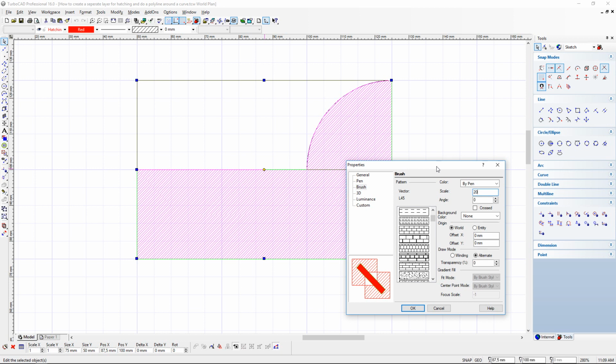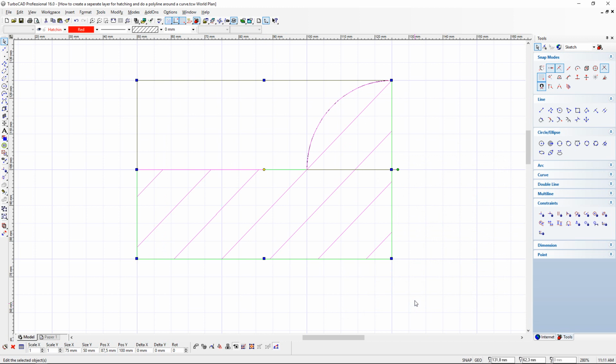But now in front of us we have a 2D drawing, therefore the hatching must be at 45 degrees. So I'm going to leave that as a default, as it is given. I'm going to leave my hatching as it is here. All I wanted to change was the scale of the hatching, that is to spread out the distance between the 45 degree lines of my hatching, and this is the result that I get.